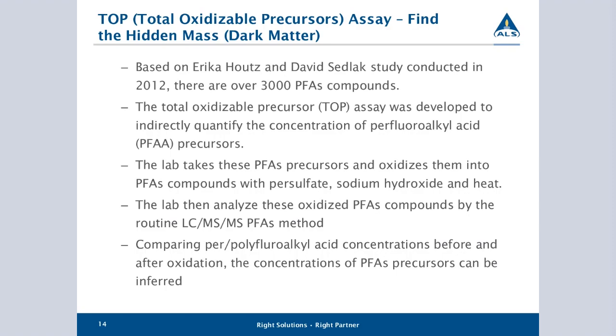So what TOP was designed to do was oxidize the sample water that we receive in the laboratory to force those precursors to become the PFOS compounds that we can analyze for. So we cannot analyze for the precursors, but we can analyze for their oxidative state. So the lab takes the samples, which have the PFOS precursors, and we oxidize them with persulfate, sodium hydroxide, and heat for about 8 hours, and it forces those precursors to become the PFOS compounds that we